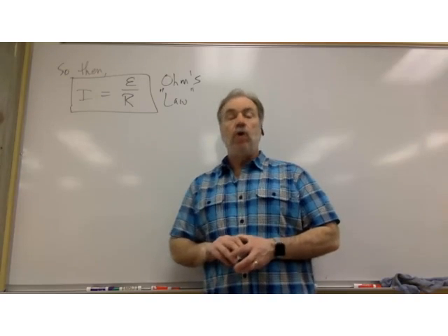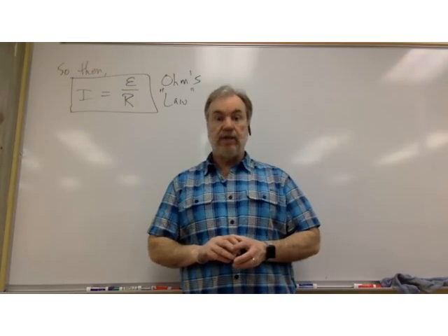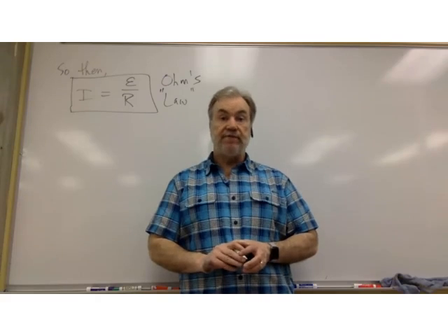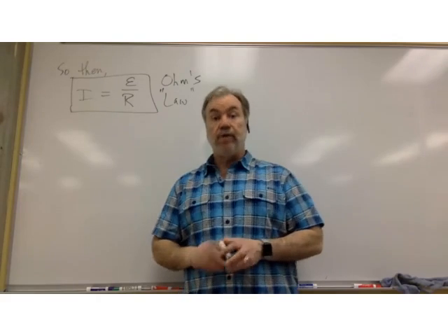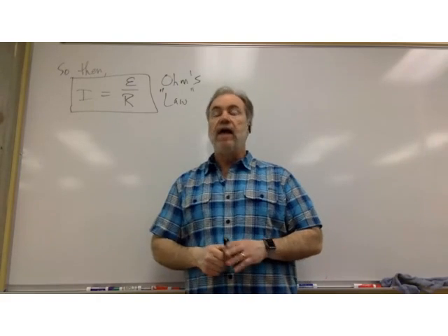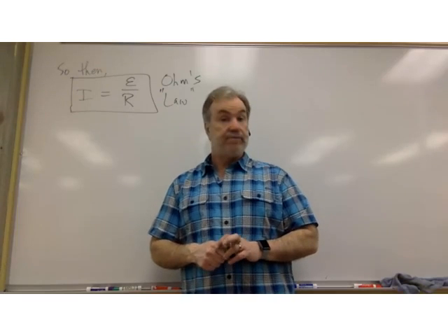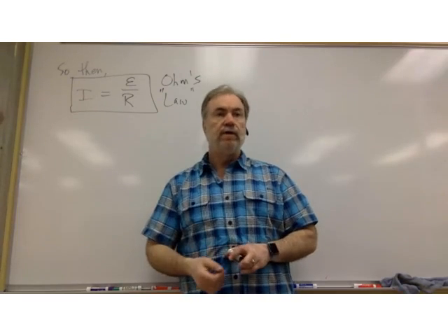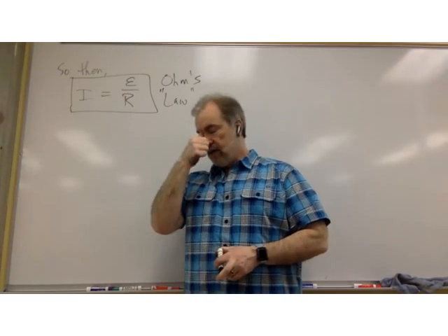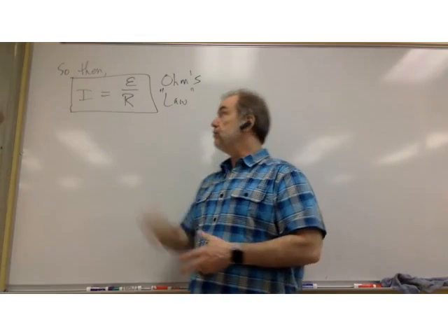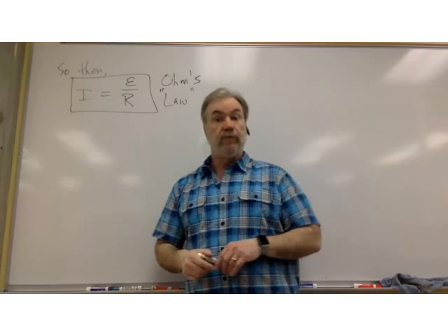It should be called Ohm's observations about a limited collection of materials under a limited set of circumstances. Somehow that's not quite as catchy as Ohm's law. But please be aware, Ohm's law is only applicable over a comparatively small number of types of materials: copper, silver, gold, aluminum to a lesser extent, over a limited range of potential differences or EMFs. But on the other hand, when it works, it works really well.